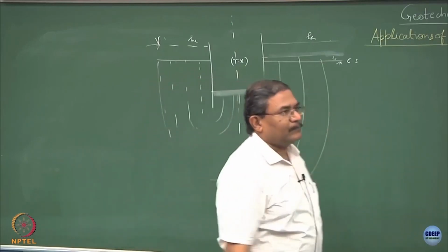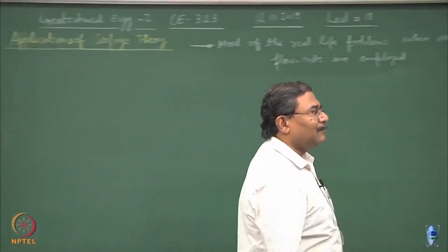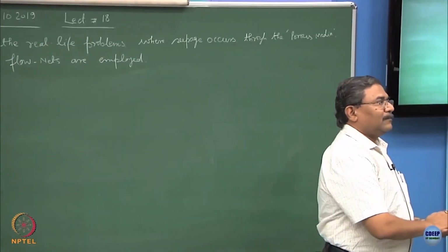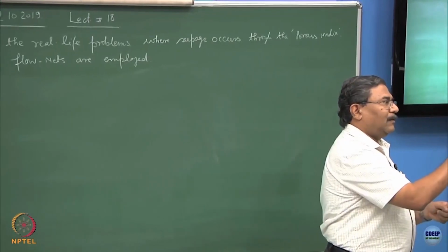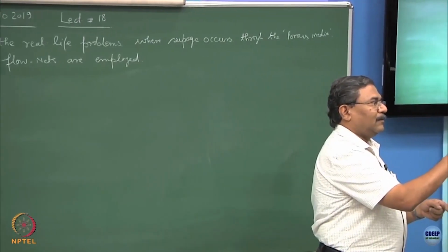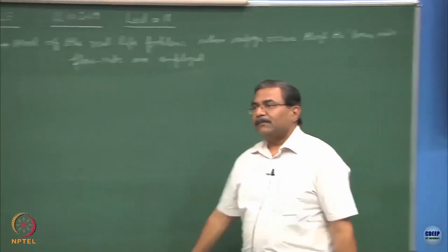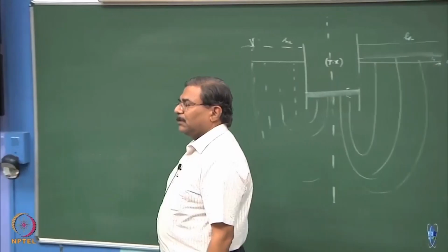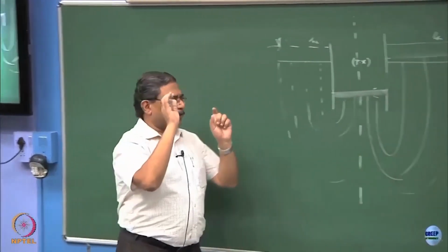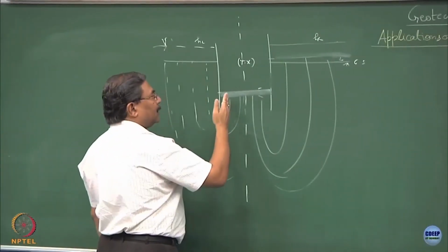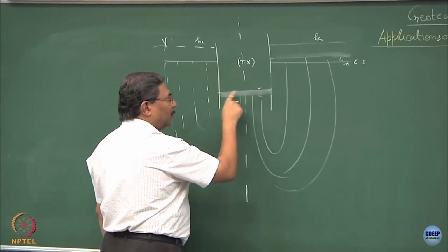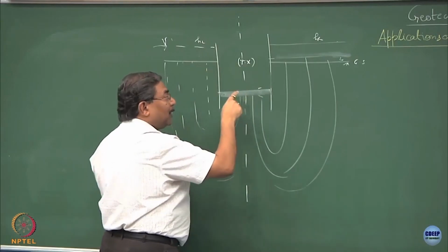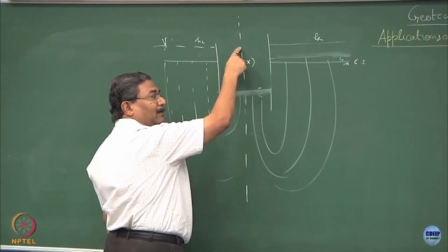What type of boundary condition would this be now? Flow lines coming and hitting a plane, equipotential. Is this part clear? Just go by the simple geometry of the thing. The flow lines come and cut a certain plane, which is going to be an equipotential. You have an equipotential here, you have an equipotential here. This equipotential is connected to the atmosphere.